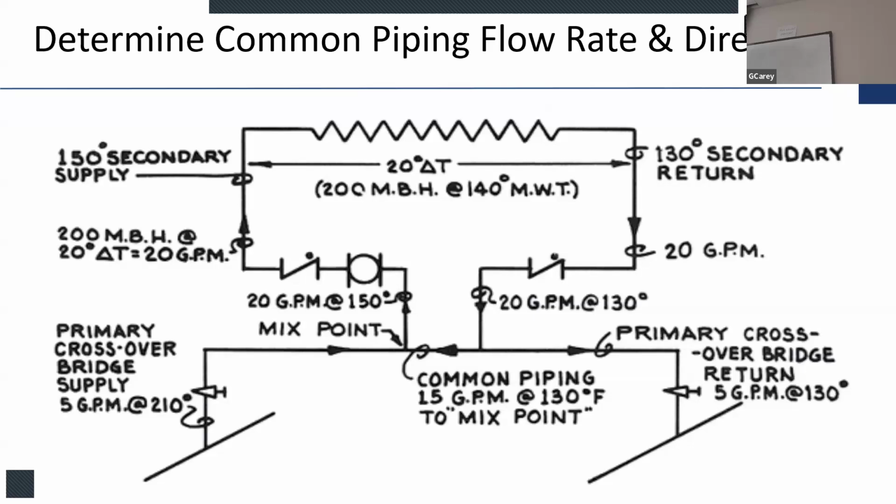No, that's a pump. Well, this right here, this is the primary. We'll call it whatever you call it, primary, secondary. This is a two-pipe system, a supply and a return, and he's got a crossover. That would be balanced based on right here that you can't see. I've got this big distribution pump that's feeding, say, a bunch of bridges, a bunch of crossovers. But he doesn't care about the flow and the terminal unit pressure drop up here. That's going to be taken care of by this guy here.